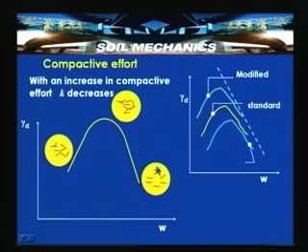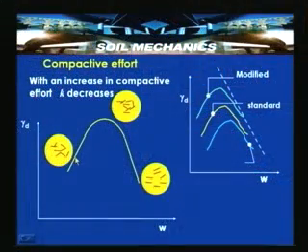By using the same logic we discussed, the permeability value on the dry side of optimum will be very high compared to the wet side, for soil with the same void ratio or same dry unit weight. The soil with a flocculent structure can have higher permeability compared to the soil with a dispersed structure. The discussion we already had is because of the type of the soil structure prevailing at that particular void ratio.